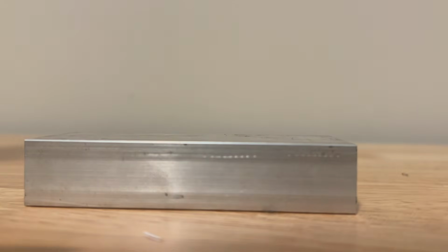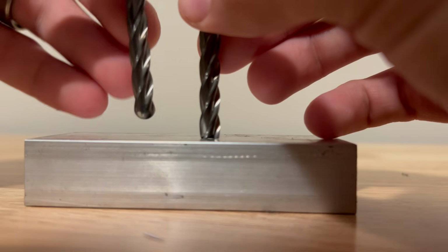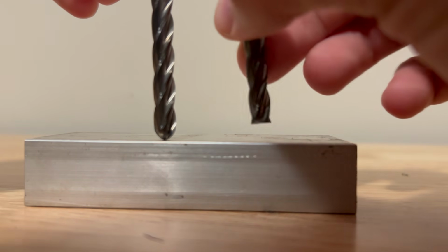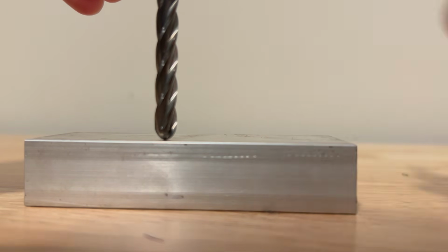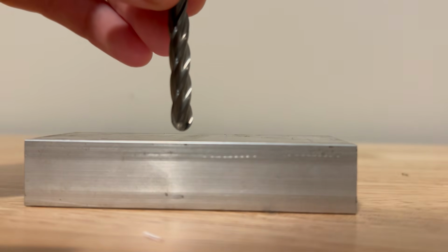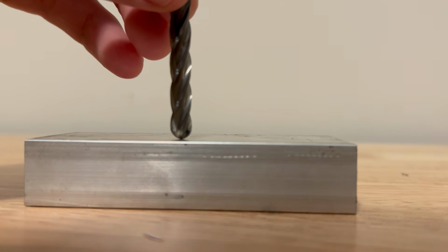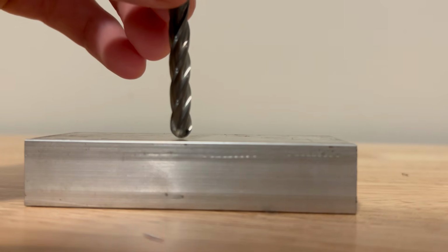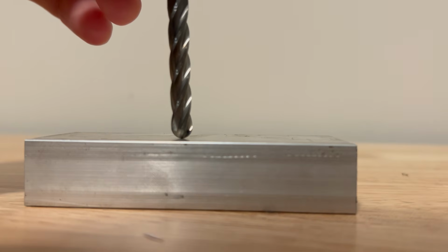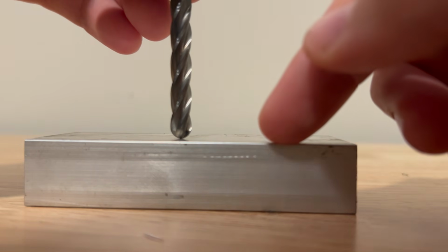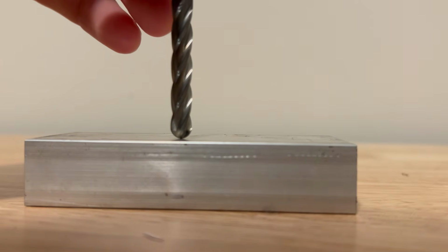So if you wanted to make something that's not flat, you would use a ball nose end mill for finishing. You can rough the non-flat surface with a flat end mill, but the ball nose end mill will give you that super smooth finish on angles, radius, things that aren't flat. So you also need a ball nose end mill and probably a radius cutting end mill if you want to put fillets or anything round on the top edges of your parts.